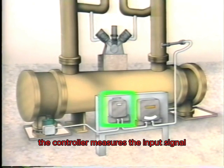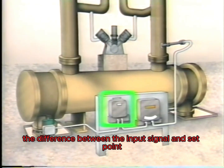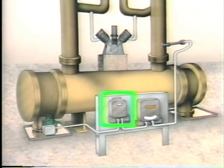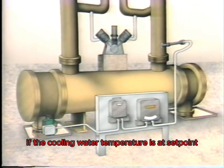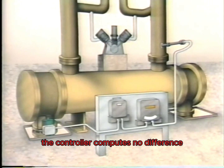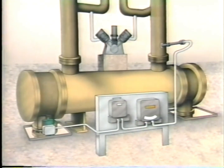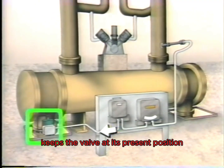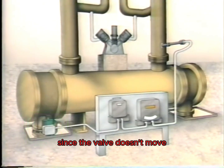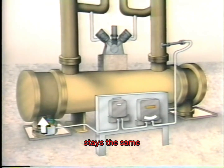The controller measures the input signal, compares it to set point, computes the difference between the input signal and set point, and produces a pneumatic output signal, which it sends to the final control element. If the cooling water temperature is at set point, the controller computes no difference between the input signal from the transmitter and set point. And the signal that the controller sends to the final control element keeps the valve at its present position. Since the valve doesn't move, raw water flow through the heat exchanger tubes stays the same.